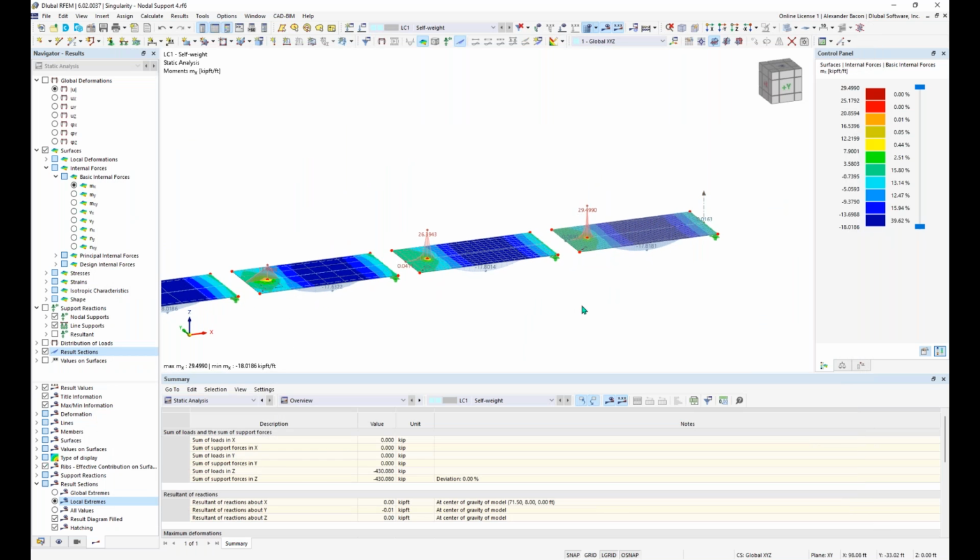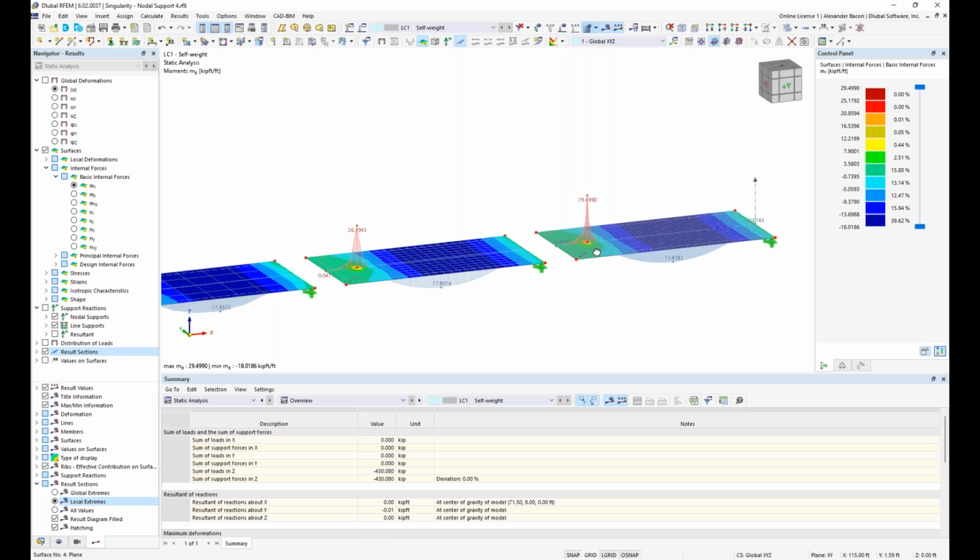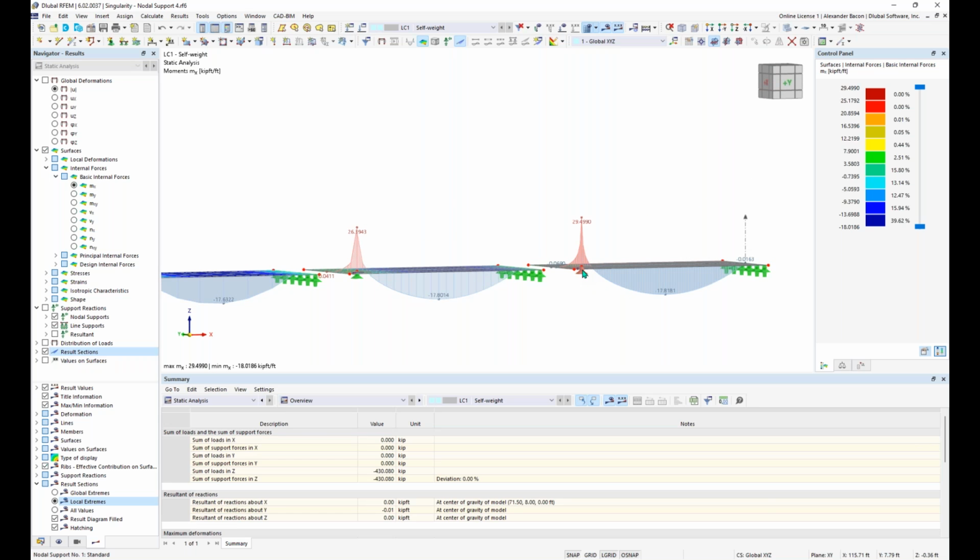And that range would be the length of whatever element is connecting into the surface here, what this node's supposed to be representing. Or you can change your supports from something infinitely rigid, like what these are set to now, to something that is less stiff. So the stiffer the element, the more loads they attract.